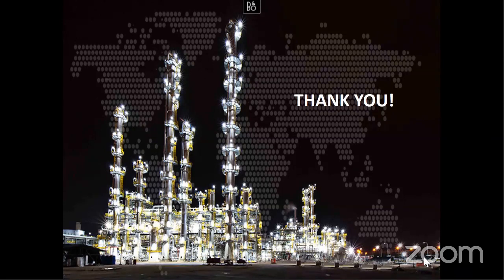And what the difference with that is, instead of having my gateway hanging on the wall, where the distance is only so far, it can go 100 feet, let's say. It can't talk to a light 1,000 feet away, but if it can talk to the next one and the next one and the next one, it'll all connect back. And the beauty of that is it's self-healing. If you have a failure somewhere in that string, it'll just bounce around and find its way back. The technology is very similar to what they use for lighting in your house, if you buy the smart Philips light bulbs or whoever makes those these days.